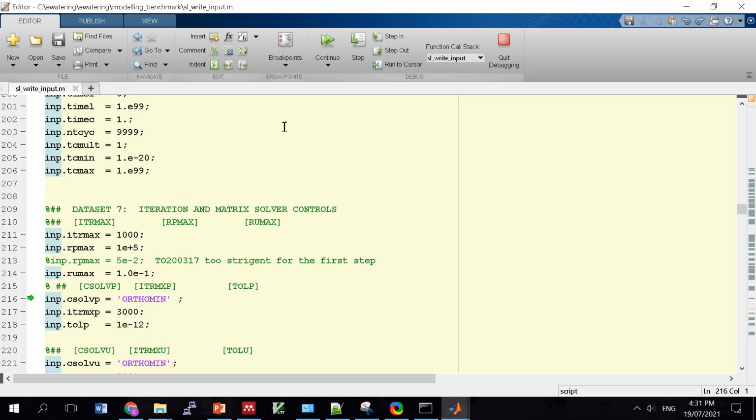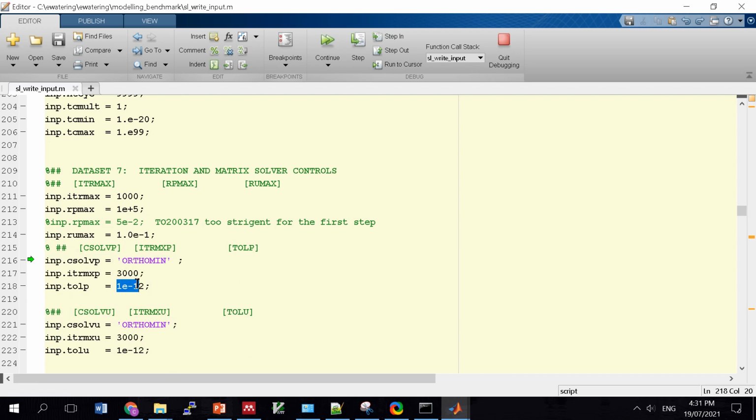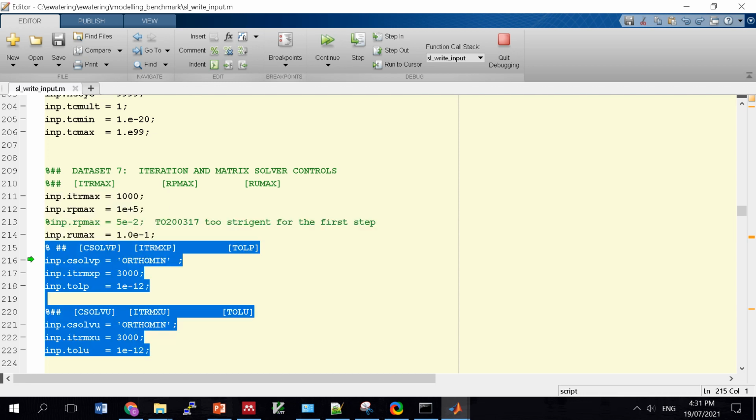These numbers, I would always suggest you use these numbers. I've never changed these numbers most of my time. So that's the internal convergence criteria. I sometimes find that if you try to increase this number, it will make your simulation not accurate enough, so always use that number. There are stories between these numbers, but you start off changing them when you realize your simulations are always difficult to converge. I normally don't change these numbers at all.